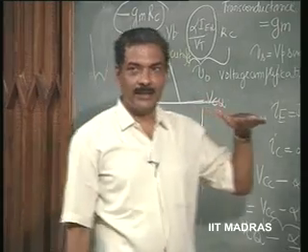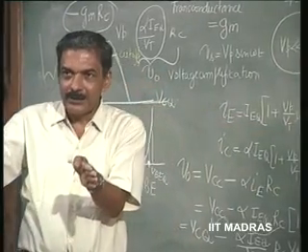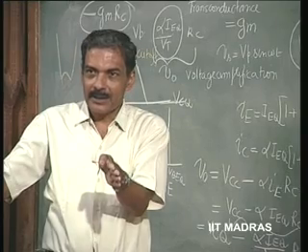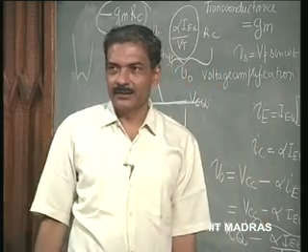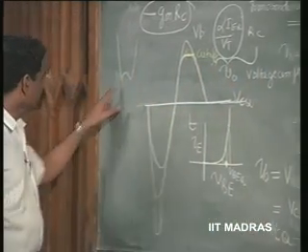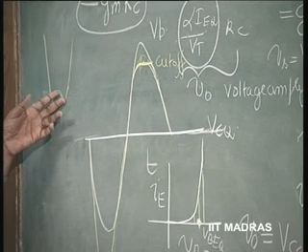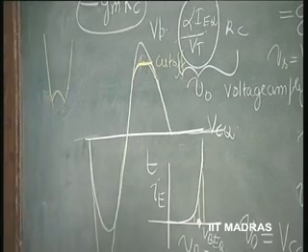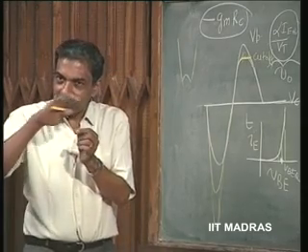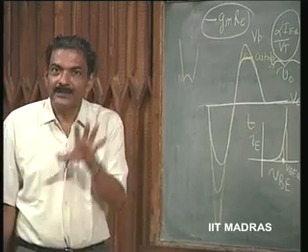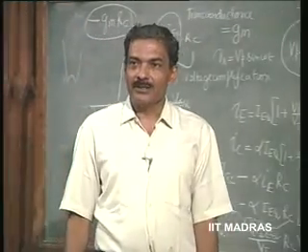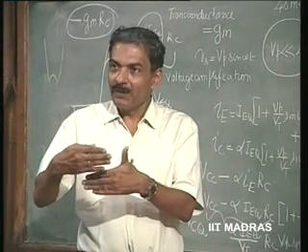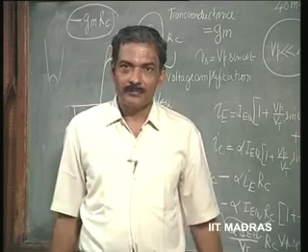When it is cut off, it is just almost chopping off, because there is no further voltage increase that can occur. When it is in saturation, this signal still appears, but its amplification factor is not at all there. It may appear just as such, whereas this is the amplified signal. So, you might not really see that increase there, or it might appear almost flat if it is a good amplifier. If it is a bad amplifier, you will clearly see that it has gone over to saturation, because there is going to be this flip over of this portion of the signal. Is it clear?